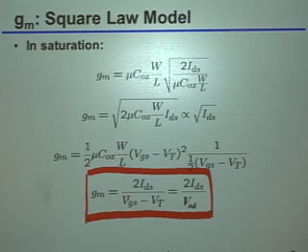Okay? And oftentimes when we talk about VGS minus VT, we refer to that as an overdrive or VDSAT. Those are all kind of equivalent names for the same thing. Okay? So as you'll see in 1 second, we're actually going to use something that looks very much like this form throughout the entire class, but we're going to use it for devices that are by absolutely no means square law. Okay? So we're going to have to make a small tweak, so to speak, to make that work. But keep this form in mind, because indeed it will be very, very useful for us.